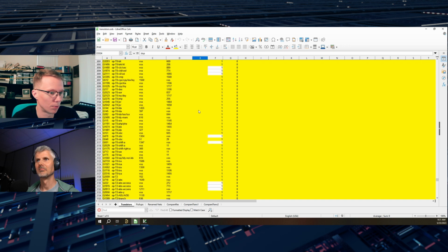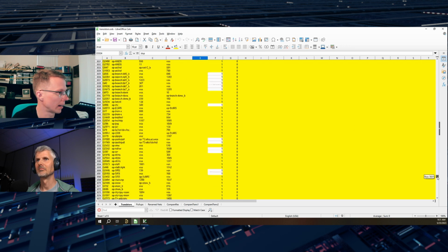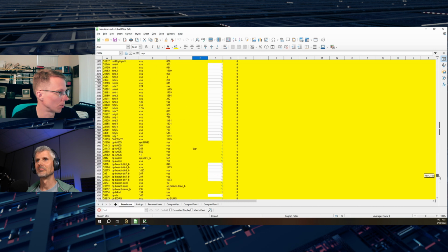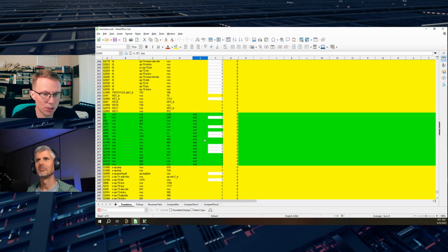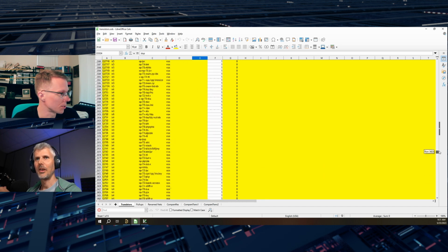There's also a couple of rows in here. I think these are highlighted in green. I found some earlier. There we go. These are actually just ESD structures, and so they're connected as ESD clamps on the pads. In that sense, they're not really useful for the MOnSter 6502, and so I just left those out. And so that's kind of the whole list. That was all the starting point.